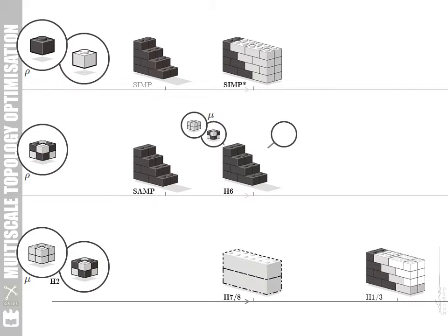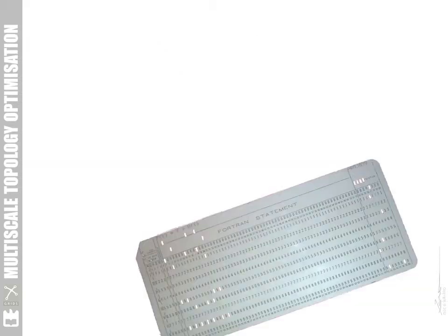We can have an intermediate problem where we can say, as is usual in composite materials, in structures made of composite materials, where for each region of the macro scale of the structure, we try to find the best material distribution, the best material orientation for that given distribution or for that given region. And this is the case for the intermediate one. We can even do another thing, which is on the limit, the lower limit, we have only one region, and we study the macro scale, but we do the optimization on the micro scale level.